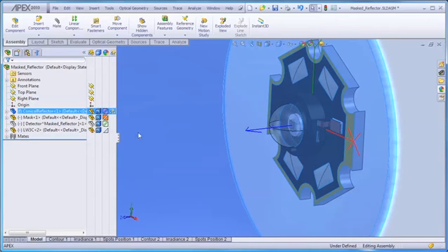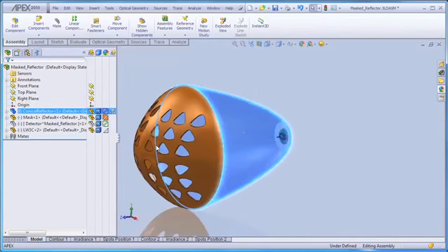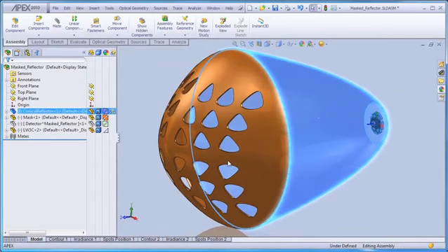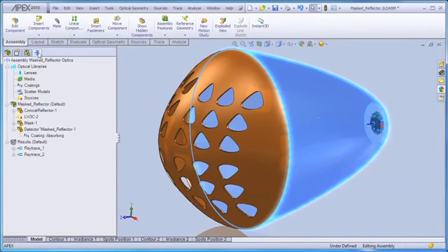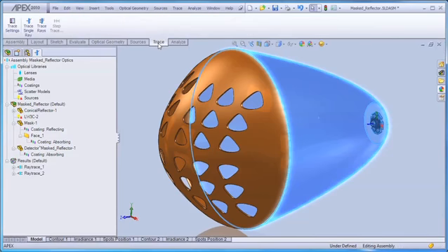Since we want reflective surfaces, we can use the Apex Coatings Manager to quickly assign an ideal reflective coating to each part in our design. Having created our geometry and source, we're now ready to ray trace the design and can use the Trace tab to check trace settings and then trace rays.